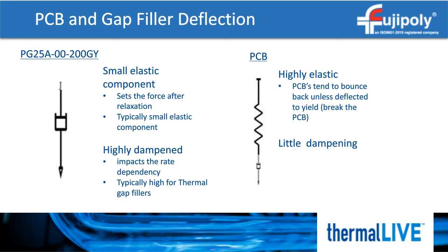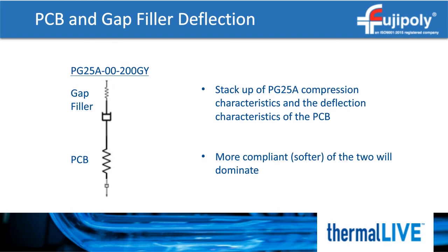In the case of our PCB gap filler stack-up test, we would look at it as a series of dashpots and springs. If we were to give these components values, the compliance of the PCB would definitely dominate. The PCB would flex under much lower loads. The gap filler's time-dependent component would mean it would require much higher force to compress compared to the PCB. In this case, the PCB elastic component would be reacting to the rate-dependent component of the gap filler. Of course, since the rate dependency means the force will eventually relax over time, it will balance out with the elastic component. If you are inclined, you can create a nice differential equation that describes the relationship of stress, strain, and time.